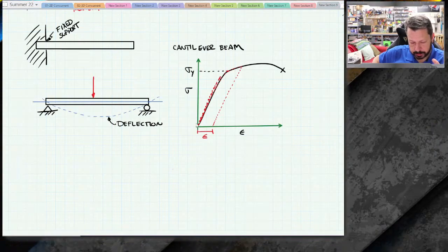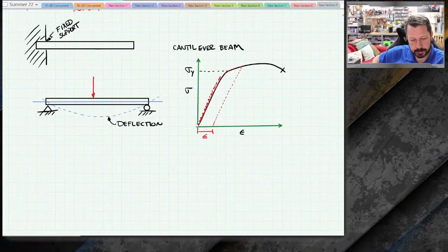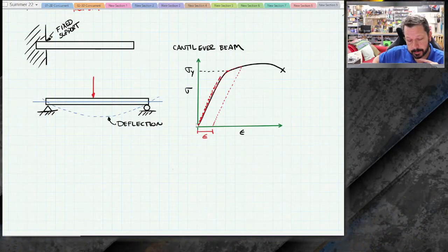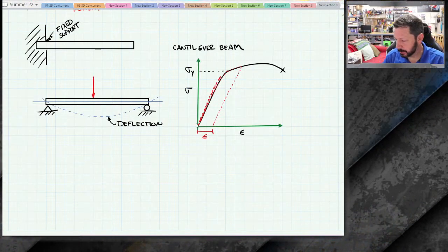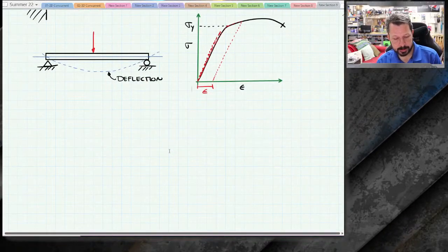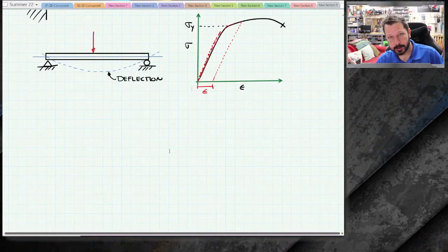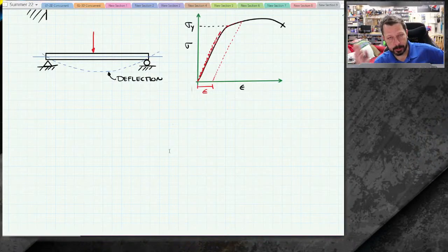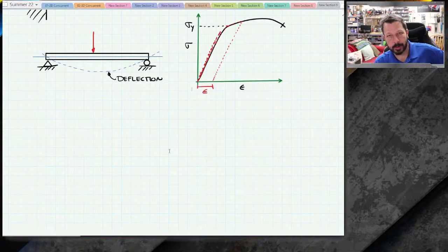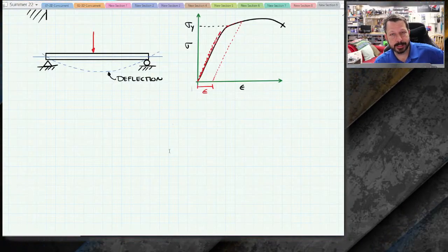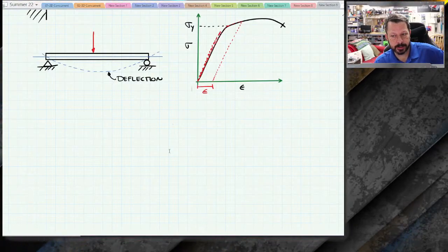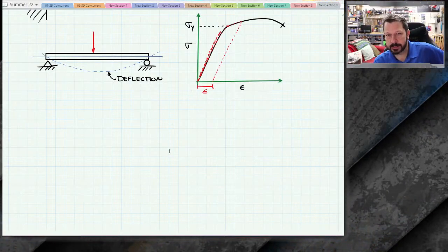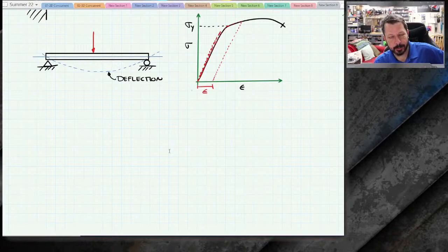These deflection stresses, there's internal bending stress, there's internal shear stress. There's two types of internal shear stress actually. All of that is internal. So I need to know, just like when I was doing the axial stuff and we would cut a plate or a rod open and look at the forces inside it to see if they were tension or compression, we need to do the same thing here, except now the forces aren't quite the same as they were before.